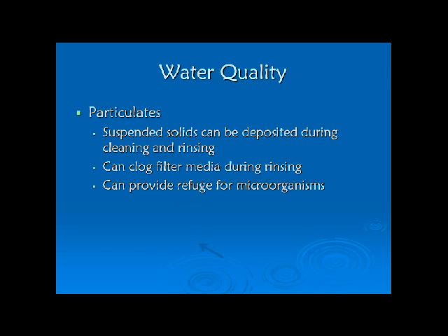So moving on, particulates, of course, they don't look good in the water. Suspended solids give it a haze, make it look unattractive, which even if there's no other problems with it, doesn't look like anything can get cleaned by using it. And in fact, these suspended solids can be deposited during cleaning and rinsing. So in other words, you're hosing down a tank and a little bit sits somewhere. If it doesn't run off completely and fast enough to keep those in suspension, they can settle out, and you can have what you think is clean now has a film on it that's been left by this water.